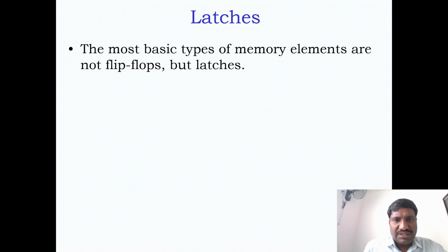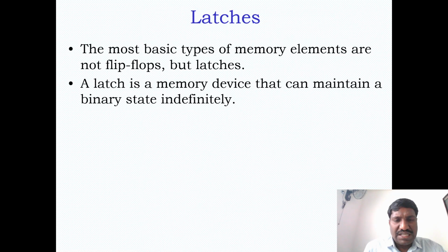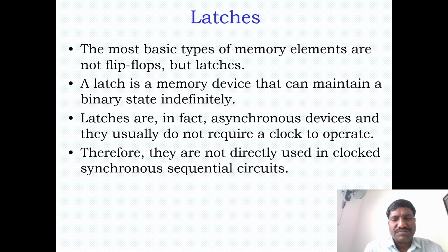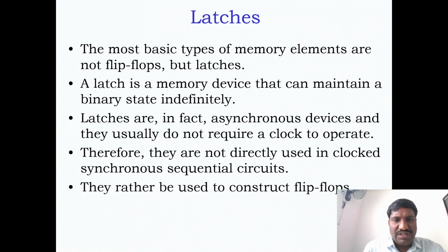So we are going to deal with latches. A latch is a 1-bit memory cell. Its operation is not based on the clock. It is an asynchronous memory device which can store 1 or 0. In synchronous sequential circuits we are going to use clocks. We will build the flip-flop with the help of latches, so the basis for all flip-flops is the latch. To start with flip-flops we should know the latch, so we will start with the latch.